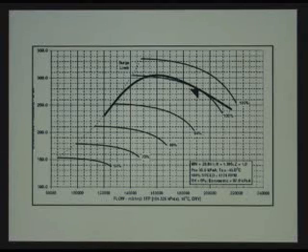Now that's not anything that's normally programmed in any kind of control system. This would be extremely unique. The other thing is, at this point of inflection, when you open your valve up, you don't know if the process is going to go this way or that way. So this becomes completely uncontrolled at this point of inflection. So that's why we would say that we would have to cut this machine off at this point and say that's the actual lowest operable flow rate that we could expect out of this machine. That may be acceptable to us, it may be not. If we still need to be able to get to this point on flow, then this machine would not be acceptable.